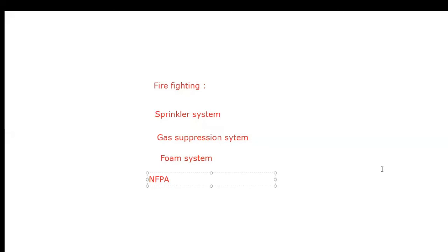So based on the purpose or the nature of the building, a firefighting engineer is going to suggest, okay, this will be the system. If you are considering a sprinkler system, at what distance we have to fix two sprinklers, or what should be the maximum distance we can maintain between two sprinklers, what type of supports we have to provide for the pipes, and what type of supports for the sprinklers. Sorry, those things also the firefighting engineer will be suggesting to the client.